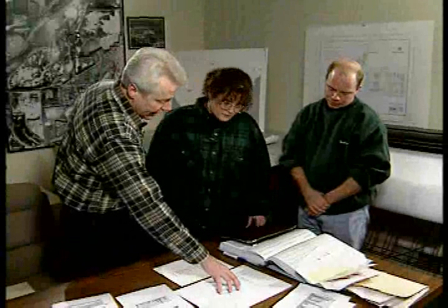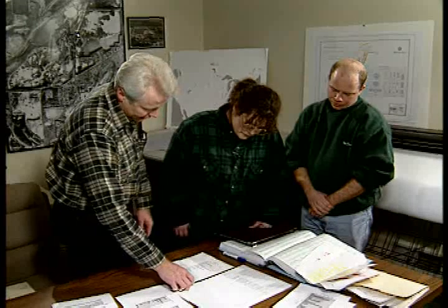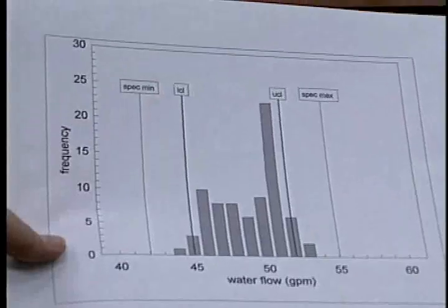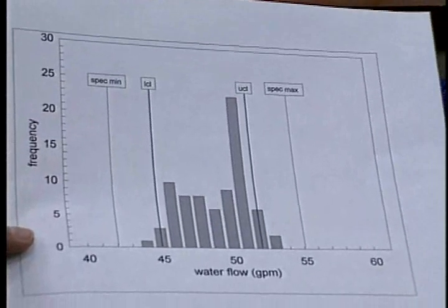These are readings from our dust collection performance system where we evaluate the manometers and U-tube gauges, and then we track this data and graph it so we can predict any potential problem areas. Yes, I can see that you're using charting to show what's going on, but it's very clear to me that it's important that the information you collect be reliable and regular. I'm sure there must be times when your job calls you to do something else and you just as soon not write down the readings in the logbook.